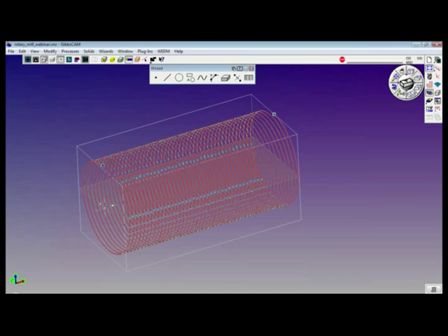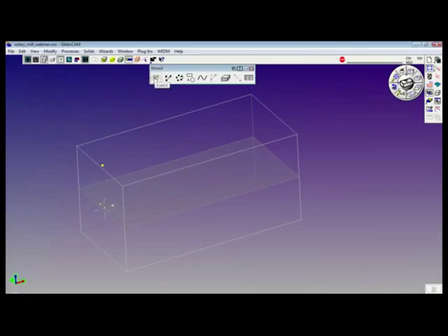Double click. I'm going to keep this point, throw this away, make a point XYZ in rotary mode. Same values, except the radius is set at 1.5, 1.25. Put the line between the points.